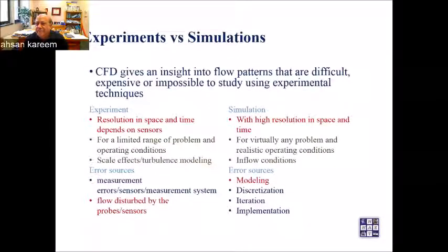So experiments versus simulation, that's always a little competition there. I would venture to say that I do both, or dabble in both. So I can say good or bad things about either one of them. CFD gives an insight into the flow patterns that are difficult, expensive, or impossible to study using experimental techniques. So here I've drawn some comparison between the two. In experiments, the resolution in space and time depends on sensors, but in case of CFD, we can have a very high resolution in space and time.